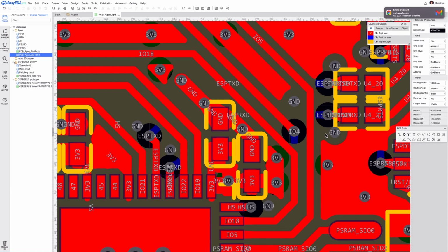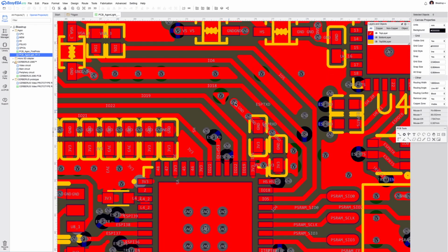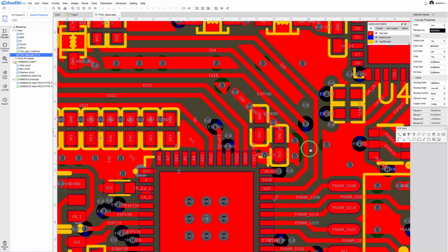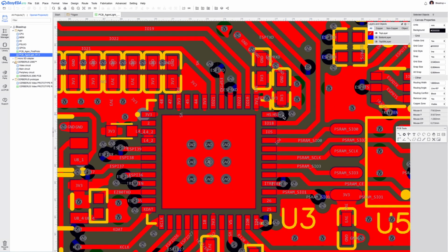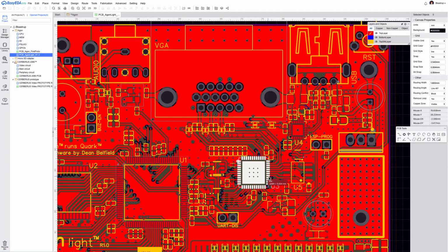So, long explanation, but hopefully it helps you understand why there are all these little vias here everywhere on this board, and some of them are actually ground, others are just close to signals. You see this one here, this one here, this one there, it's close to this one, that's close to this one, is close to that. These are all return path and reference vias, because the signals have to cross two planes when they go to the back of the board or the other way around.